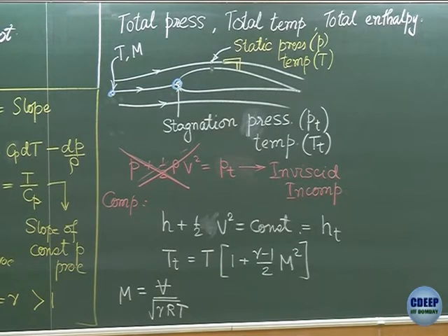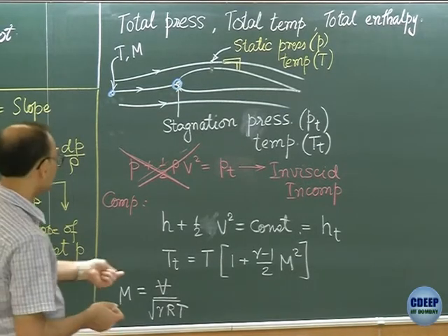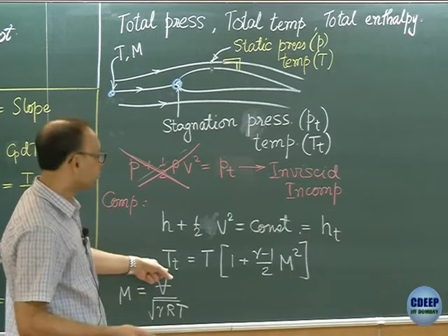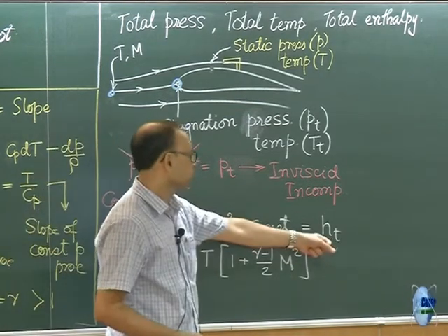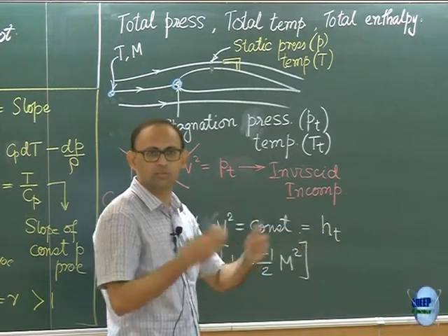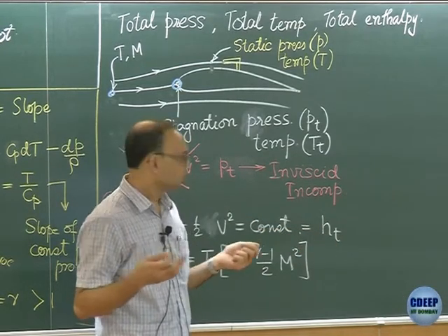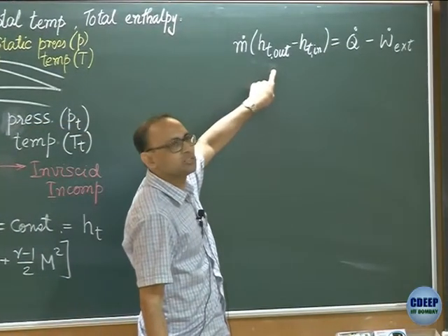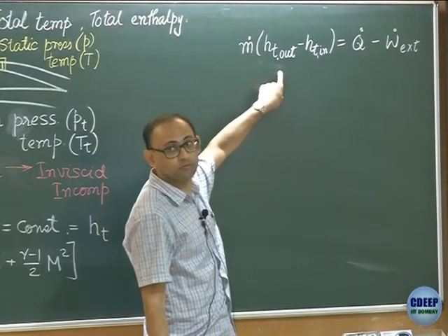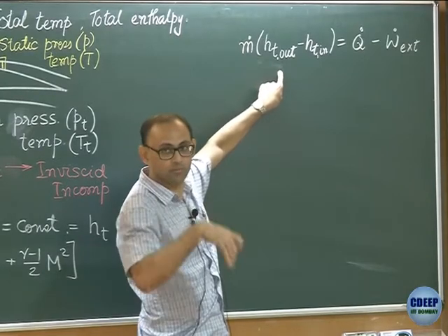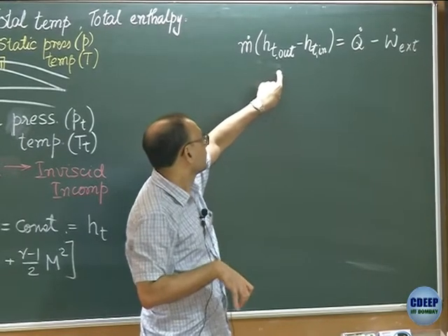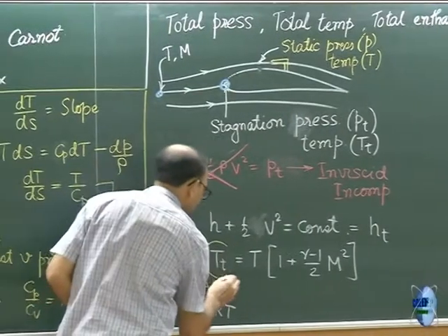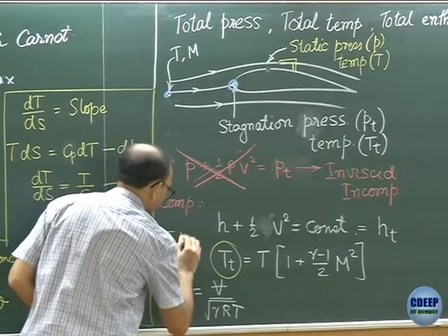So now I'm going to say that total temperature is equivalent, not equal, to total enthalpy. The two things are related by Cp. Total enthalpy, we just said, is a measure of the total amount of energy in the flow, not the fluid, the flow, because the pressure work comes in. So total temperature is also a measure of the total energy.